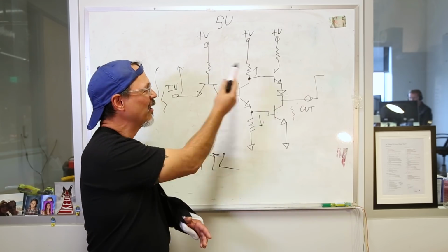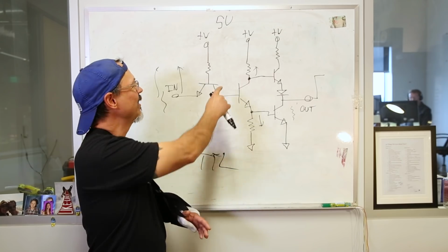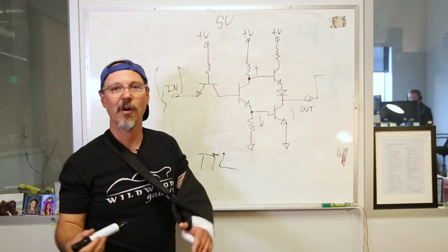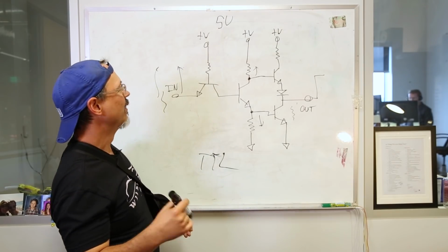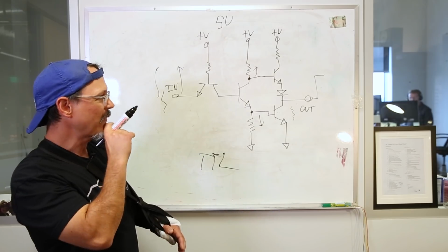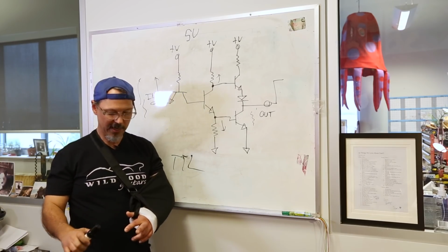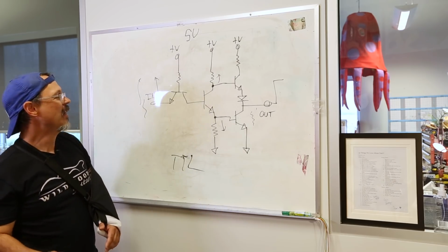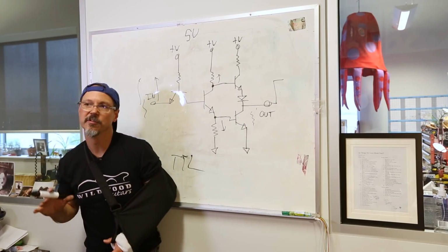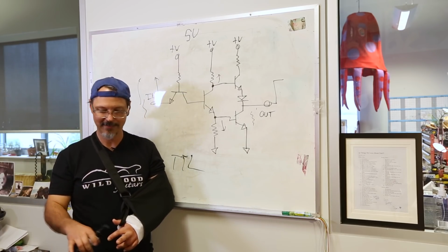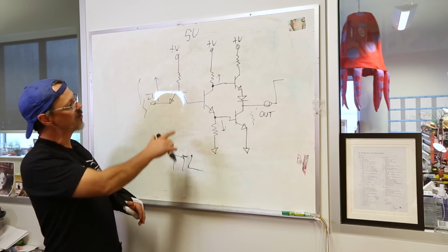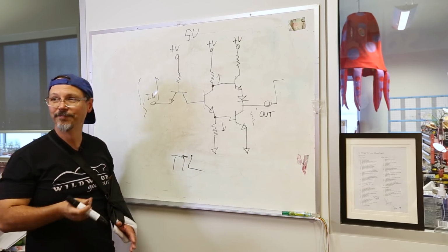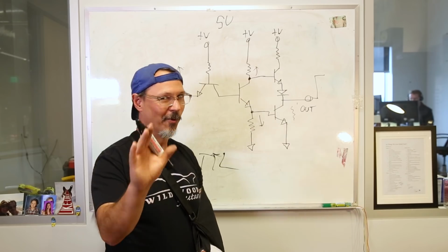You're almost certainly not going to build this out of discrete components. You're not going to take resistors and transistors. You could, but you probably won't, because you can buy something like a 7400 part, right? And we'll talk about that as we go. That will do this function for you. But TTL is slow, it's power hungry, it is a little bit noise sensitive, but it is not the optimum solution to do this with. It doesn't scale well, it sucks a lot of power, yada, yada, yada. Now, if you switch these to CMOS parts, a whole bunch of magic stuff happens, and that's what we're gonna look at next.